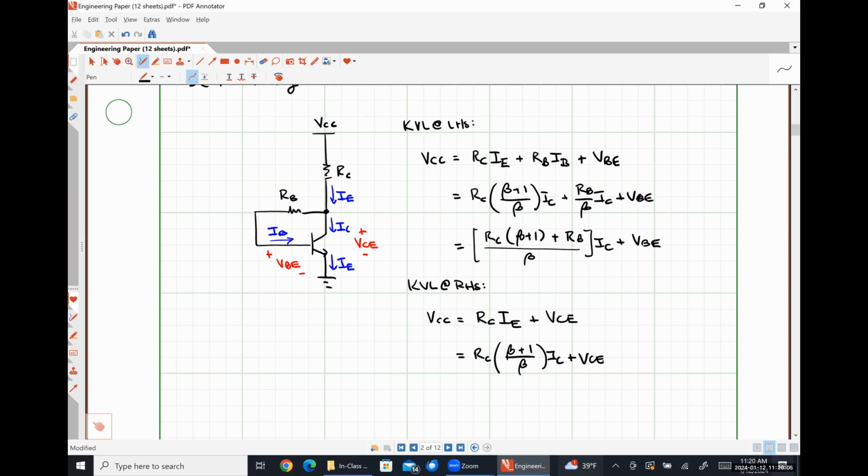All right, so anybody have any questions about these biasing networks? Yes. To ensure that it is literally impossible to knock this thing into saturation. That's it. And realistically, they're not used practically ever. We've used a 4 resistor network or the resistive divider biasing network and just design it so that we give ourselves enough headroom so that we don't actually knock it into saturation mode. We'll see.